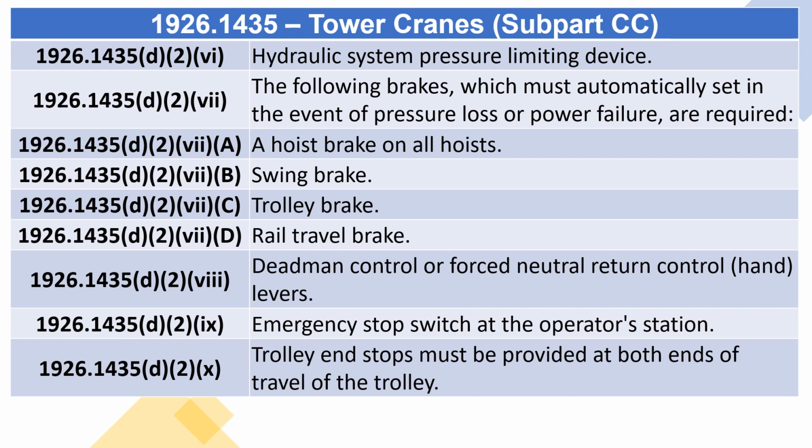Deadman control or forced neutral return control, hand levers. Emergency stop switch at the operator's station. Trolley end stops must be provided at both ends of travel of the trolley.